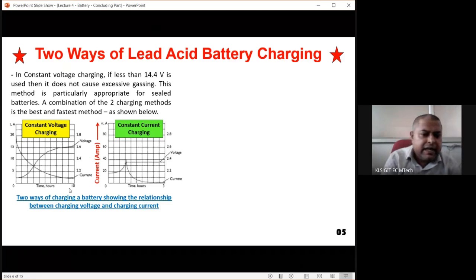hours. And the initial voltage on this is 1.1 volt, like this. So this point is 1.1 volt, and the final voltage is around 2.6 volt. So this is the voltage graph, it is 2.6 volt. We have to take it up to 2 volt, but that 0.6 volt we are giving extra. Is this graph understood, all of you three? Can you just check, because there are two axes. The left side is the current axis and the right side is the voltage axis.